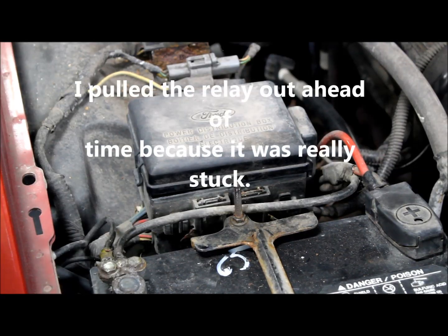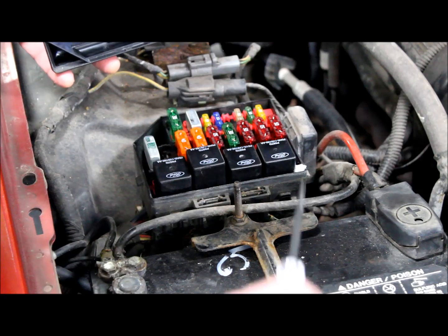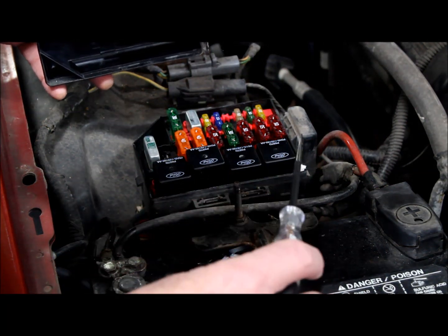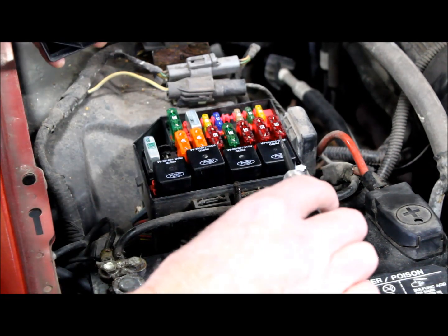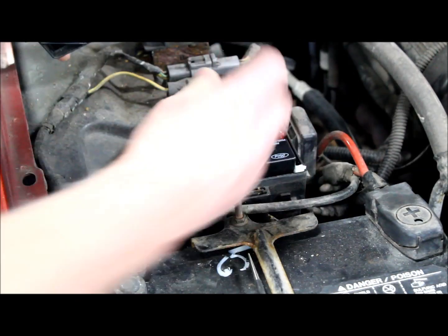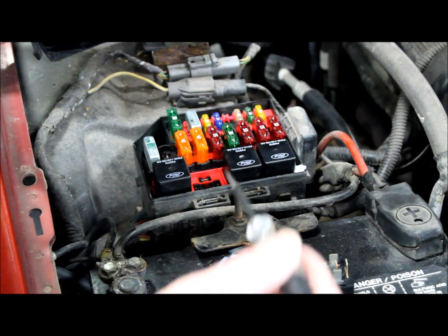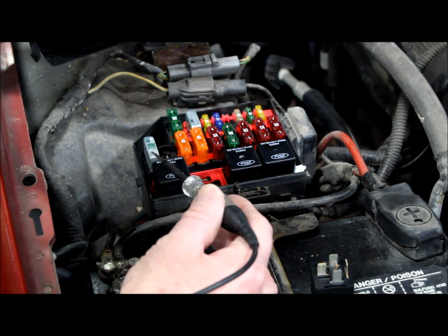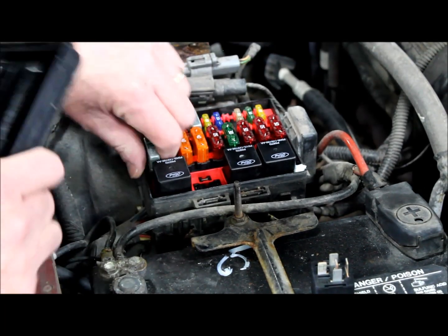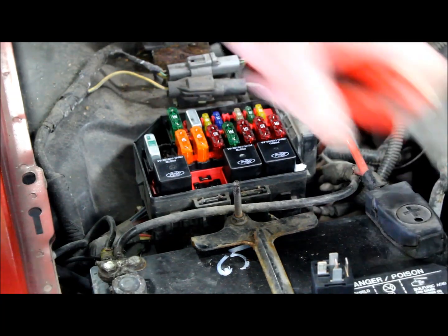So now here we are under the hood. Here's the battery junction box right here, and here are the 4 relays. We want number 3, and looking at this box we're counting across 1, 2, number 3 right there. I'm going to pull that out. As far as that number 17 circuit breaker, it's this big 30 amp circuit breaker right here. Get a better look at that. That is not easy to get out.